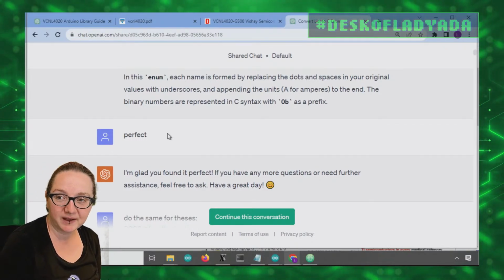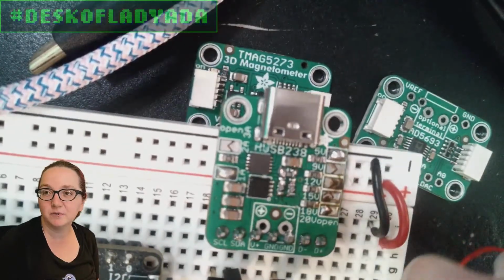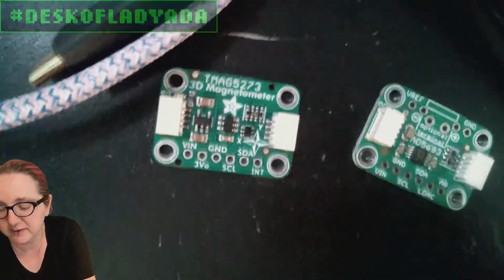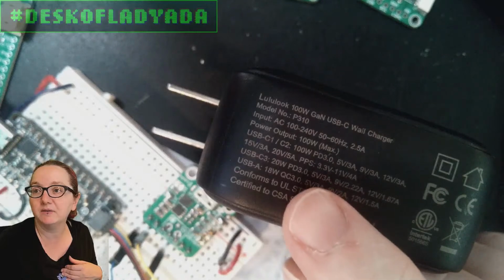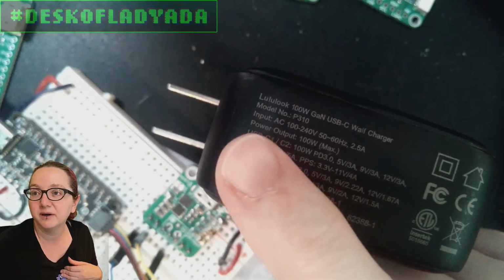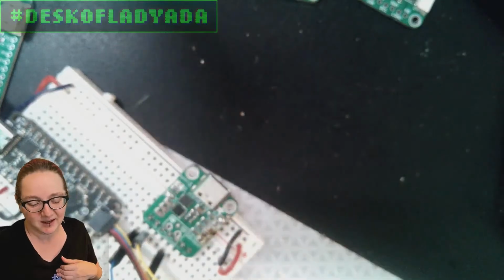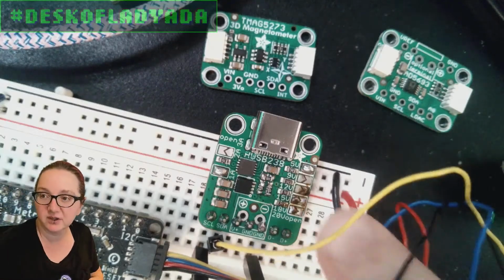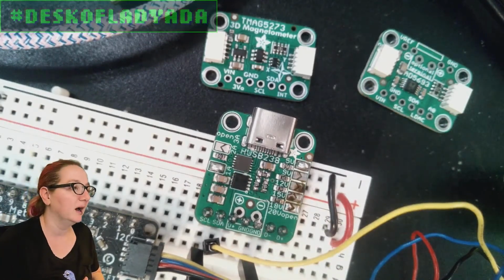I do want to show the chip real fast, now that you've seen the library, because I do have a breakout for it. This is the HUSB238, and you connect it to USB-C. It's a USB 100-watt output, and it can give you 5, 9, 12, 15, and 20 volts, up to 5 amps, 100 watts. This chip communicates with the USB-C power supply and gets you not just 5 volts, but different voltages. You can use set jumpers. You can see I've set and opened every jumper. Or you can use I2C, and that's the driver that I had to write. And it actually did a really good job.